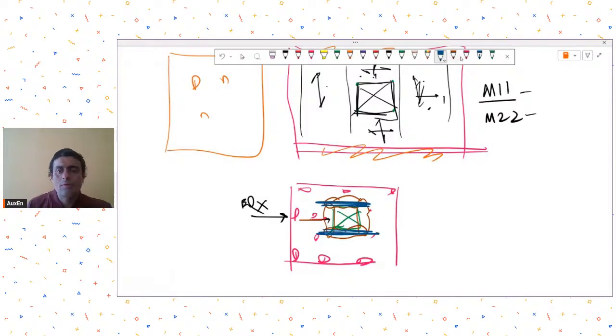So I need to see what sort of design and reinforcement I need to provide. This again you can do by modeling this correctly in software like ETABS, checking the moments and accordingly providing reinforcement. So these become your collectors and these orange things are called chords. So carefully, first of all, the reinforcement has to be checked.